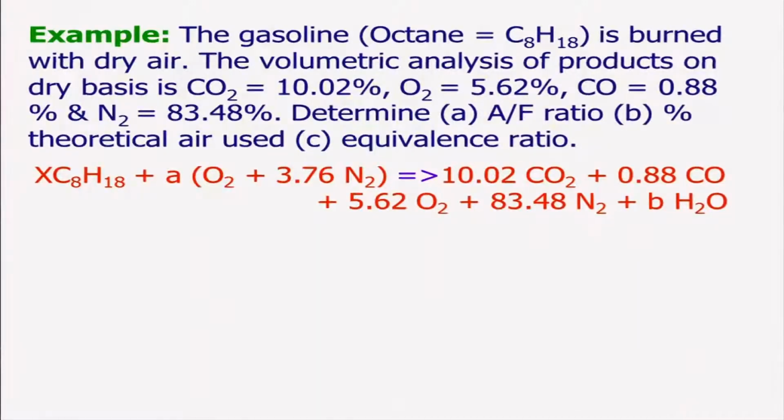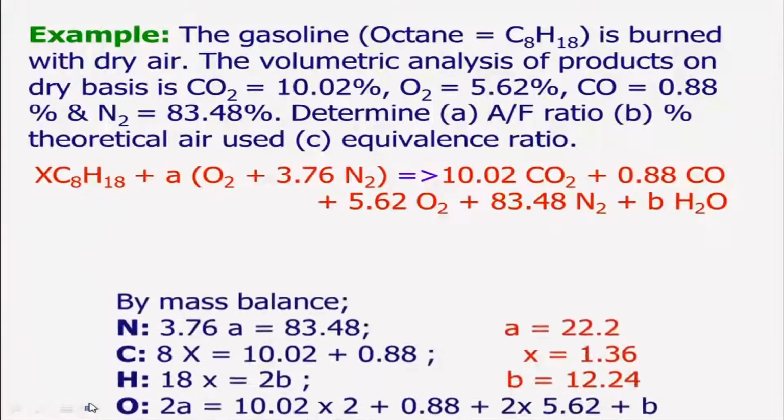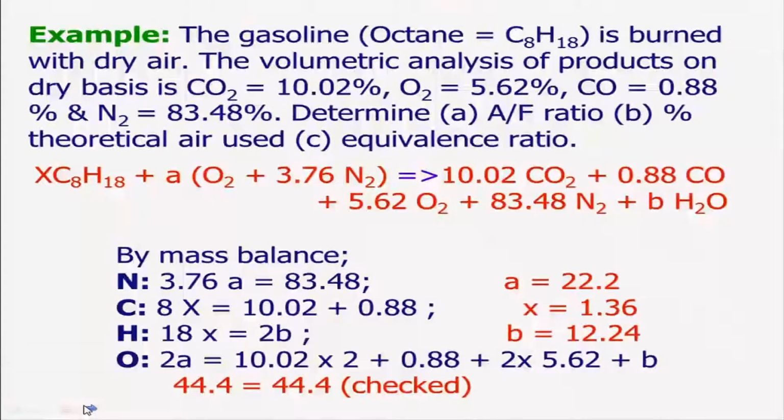In some cases the fuel will be given, a known fuel, let us say CNG gas or some other, say a producer gas. It will have several constituents. So, you need to find out like this. We will have to use a procedure which is easier and also an effective way of doing that. We will be doing basically a mass balance that we have already done, but we will do it in a little more systematic way. What we will do, we will take the nitrogen.